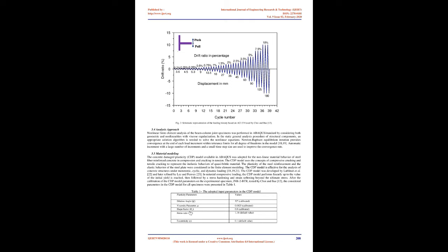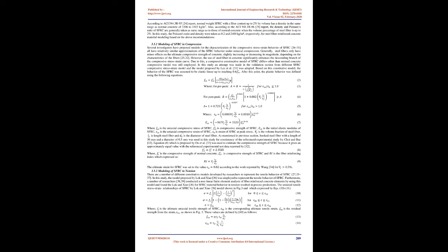To apply the boundary conditions identical to the reference experimental test setup, the nodes at the surfaces of the lower and upper column ends are attached to a reference point using the coupling constraint. The loading steel plate at the tip of the beam was constrained in Y direction for the cyclic loading application. The boundary conditions and mesh were set in the model as shown in Fig 1.